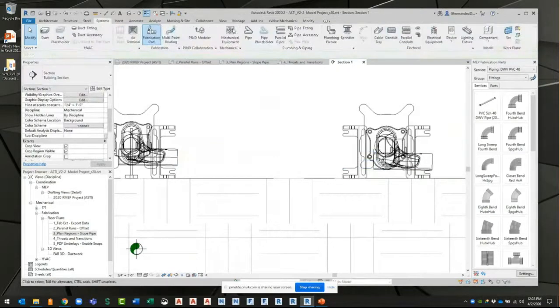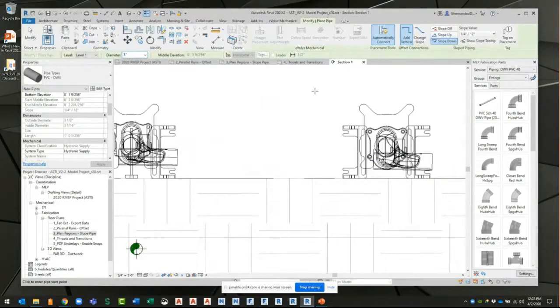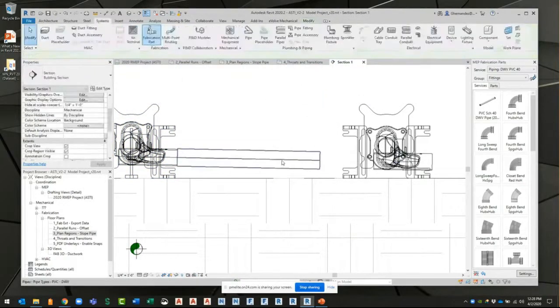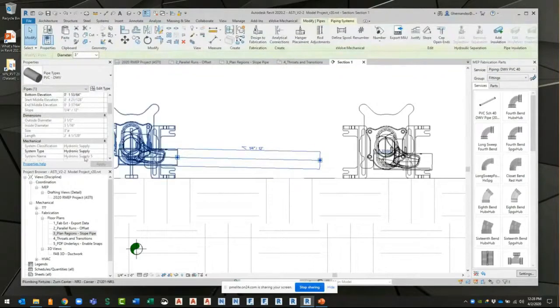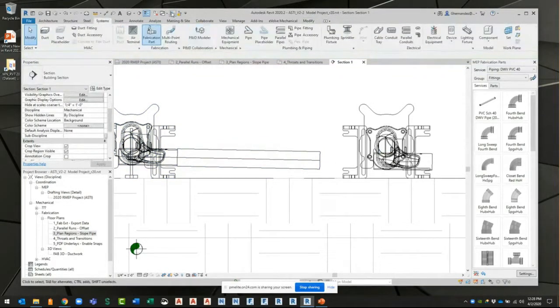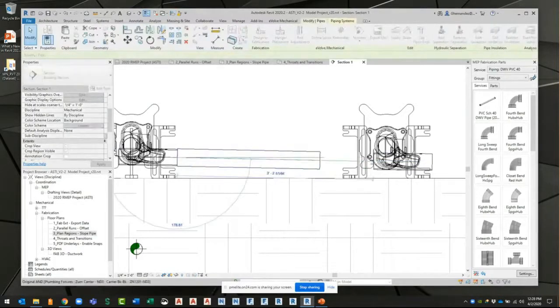So what you want to do is, and I might have been drawing from the wrong direction anyway. Let's see if this works. There it goes. Probably I was in the wrong face. So see how it's 1/4 inch here, right? And when I drag it back, I need to align this first. So I'll go to dot to centers. There. You're looking for the SX command here. SX is my snap endpoint.